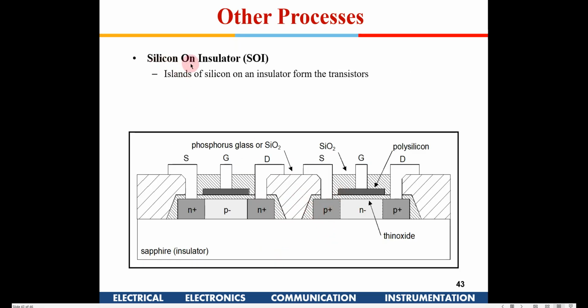And then this is silicon on insulator. Again, instead of an epitaxial layer on the wafer, we have sapphire. Sapphire is nothing but a glass kind of thing, right? So it is an insulator, and after that we deposit small epitaxial N plus and P. This P channel is also grown epitaxially. You have an insulator at the bottom, so there is absolutely no body effect at all. A lot of stray capacitances are avoided. You don't have issues like latch up and all things like that.